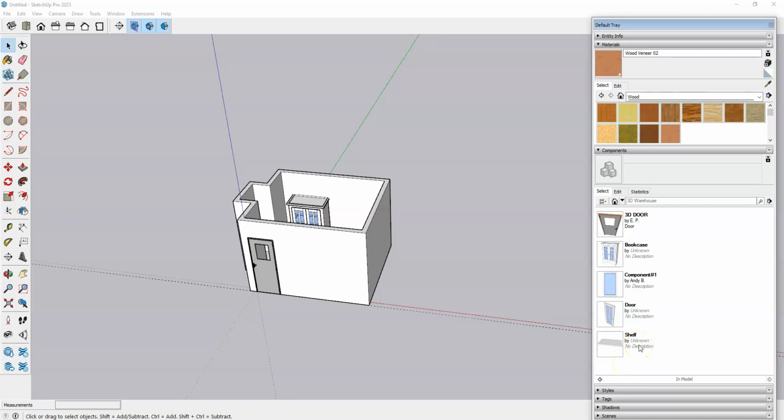So you'll see that Heather, the scale figure, went away. I didn't notice if there was anything else in here that I wasn't using, but all of those that are not inside of your model will be deleted, so it'll free up a little bit of space for you. Where was that? It was over here, this little details icon to the right of the search bar inside of this components panel. This little details button, and you'll hit purge unused. So purging removes the unused components from your model.